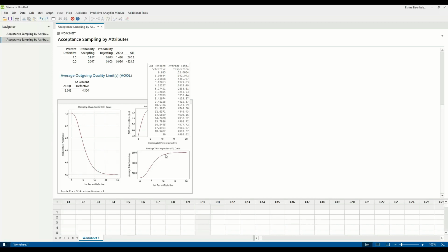So again, since we're random sampling, sometimes you're going to pass, sometimes you're not, and you never know the truth, because we're only looking at 52 items in each lot. So there might be times when you're going to have more defectives in there, but you don't see them, you missed them somehow, and that's the nature of it.